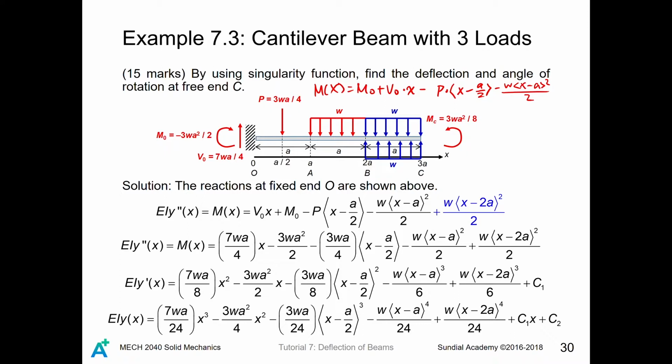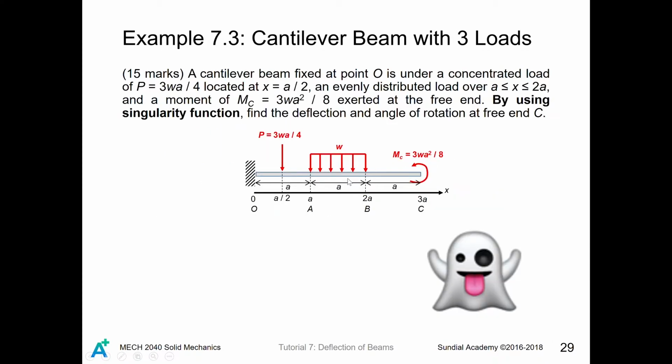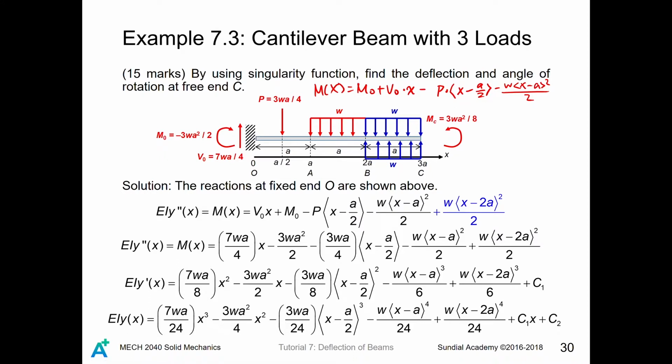Now it's time to take into consideration of our modification to the free-body diagram. The reason we add these blue things is that for the original free-body diagram, we see that there is only a segment of distributed load in the middle, but for singularity function, it will start from A and it will never stop.